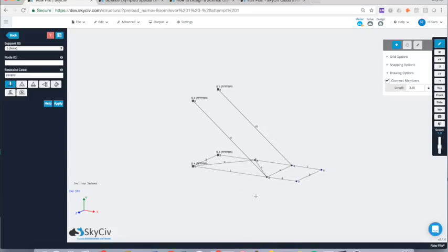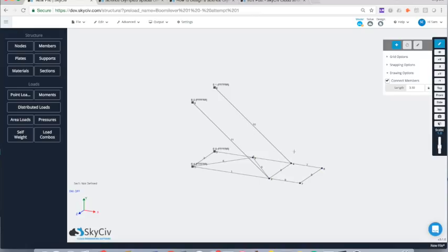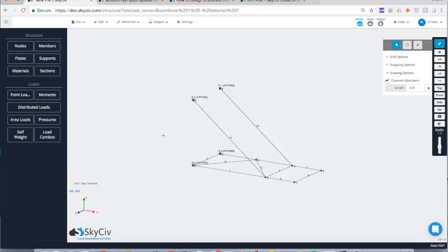And we're going to do that just on this end. So we're going to simulate the weight effects of the sand. I'm going to apply a 4 kilogram load, but I'm going to separate that into 4 point loads, and I'm going to apply them each here. So that's just an easy way. There's a few different ways you can apply loads, but this is a nice easy way that you can distribute the loads to those nodes.